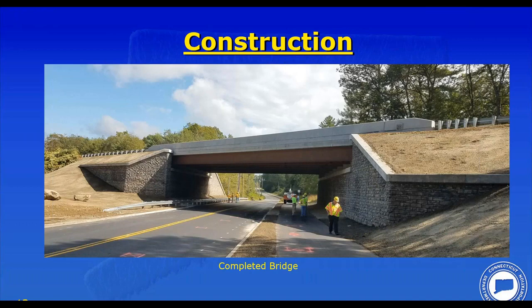Let's maybe, first of all, why was the ABC cost higher for this project when compared to the other example? Yeah, I think the key thing is the amount of time that we were saving. This particular project, with the fact that we could build the GRS IBS abutment underneath the existing bridge for both the ABC option and the non-ABC option, it took an awful lot of the construction off the critical path. And therefore, the time savings for ABC was only, I forget the number I had, it was a couple slides back, was I think 5 months or 7 months.